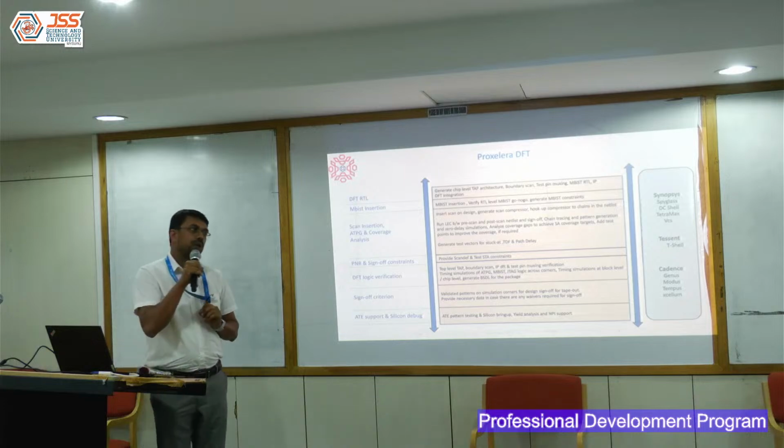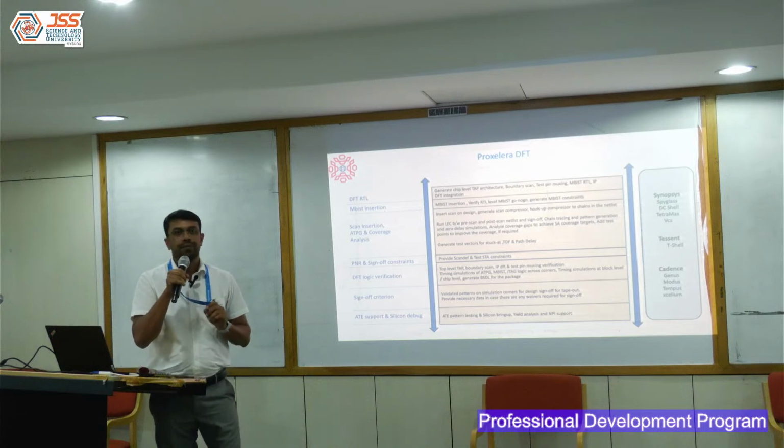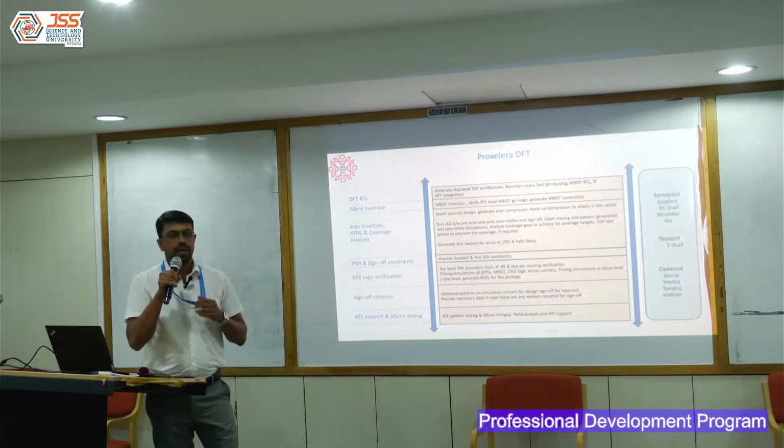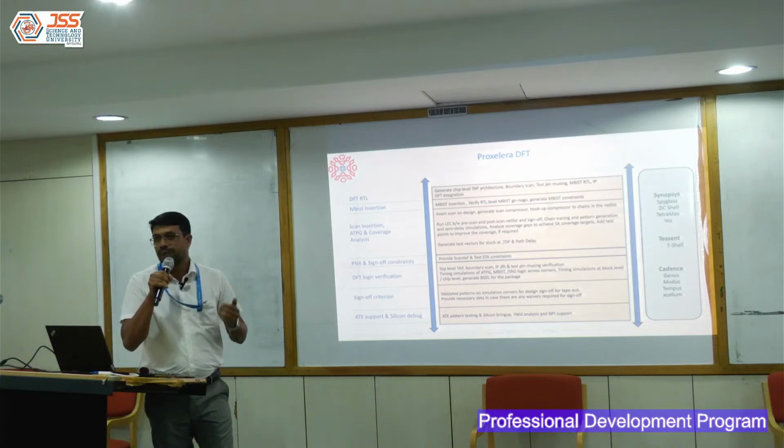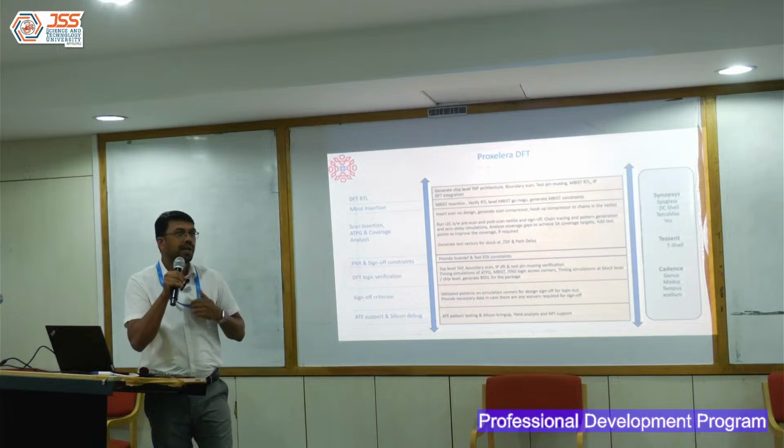So there is a terminology called DPPM, defective parts per million. If I am shipping 1 million parts, of course I cannot claim that all 1 million parts are going to be good. They have to give me a margin, and that they set very little. They say 500 DPPM. So it means that they can accept maximum 500 defective parts per million parts that I'm shipping. Beyond that, any loss that they incur, I will have to bear as a chip provider.